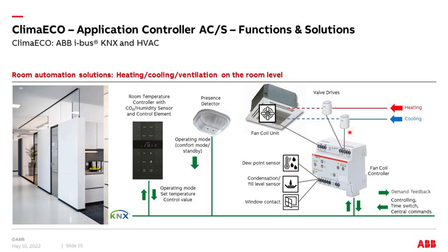Of course, we have valve control, we have fan speed control. You can integrate any presence detector to change the operating mode depending on presence. And of course, any operating element, minimum operating element to change set points, fan speed, whatever, to see actual values. Here in this component, you can have also a controller, or you have it nowadays also possible in the components in the distribution board. So this is nothing new.